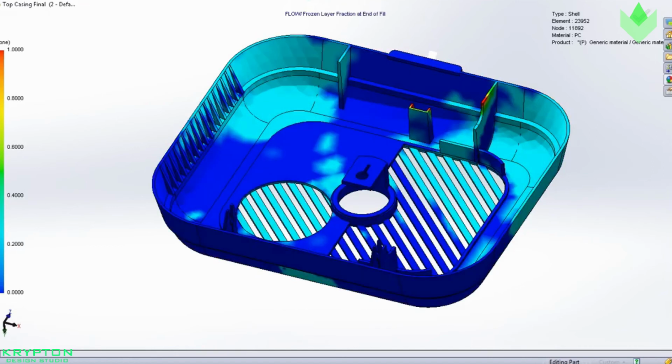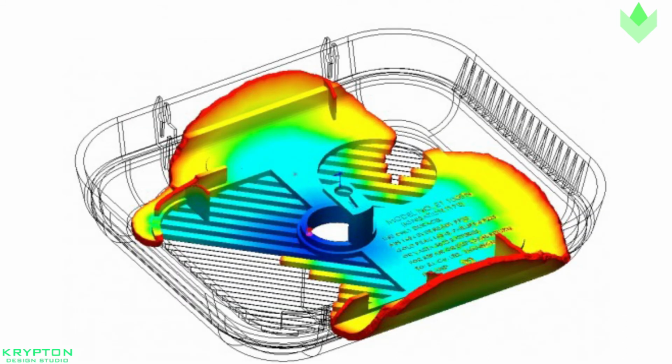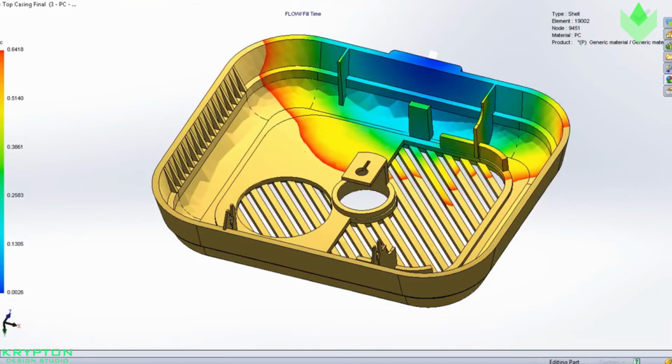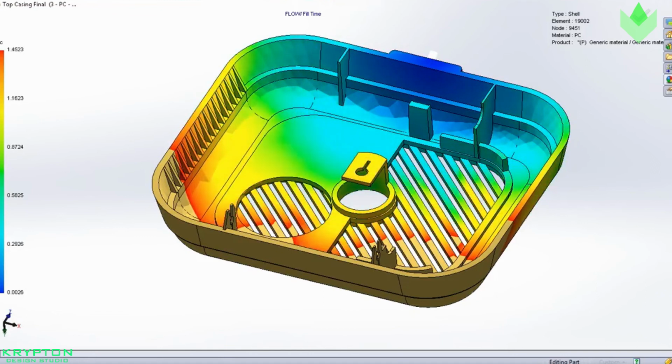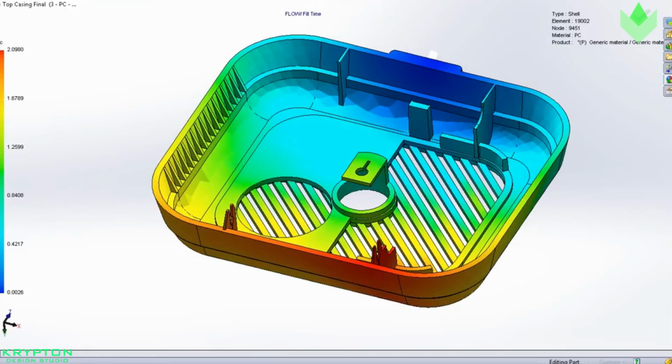In addition to being unattractive, the mark also represents added stress that builds into the part. Other less conspicuous areas where sink occurs include ribs, bosses, and corners. These are often overlooked because neither the feature nor the part itself is too thick. However, the intersection of the two can be the problem.